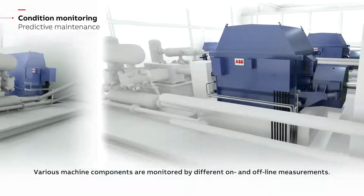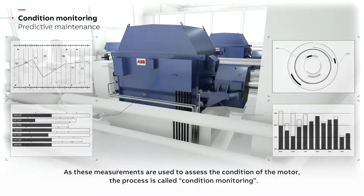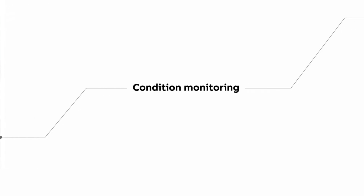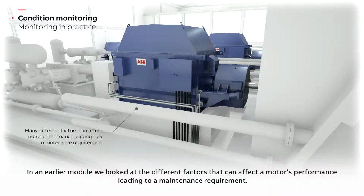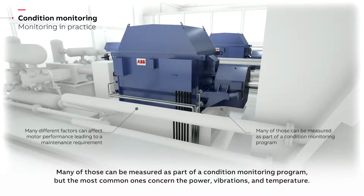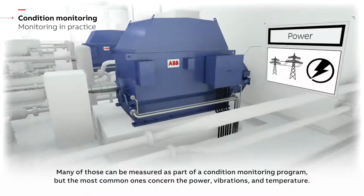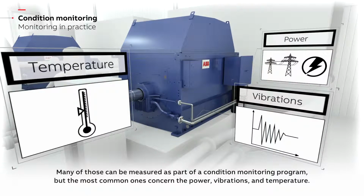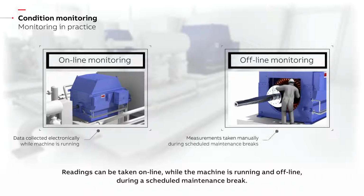Various machine components are monitored by different on- and offline measurements. As these measurements are used to assess the condition of the motor, the process is called condition monitoring. In an earlier module, we looked at the different factors that can affect a motor's performance, leading to a maintenance requirement. Many of those can be measured as part of a condition monitoring program, but the most common ones concern the power, vibrations, and temperature. Readings can be taken online while the machine is running and offline during a scheduled maintenance break.